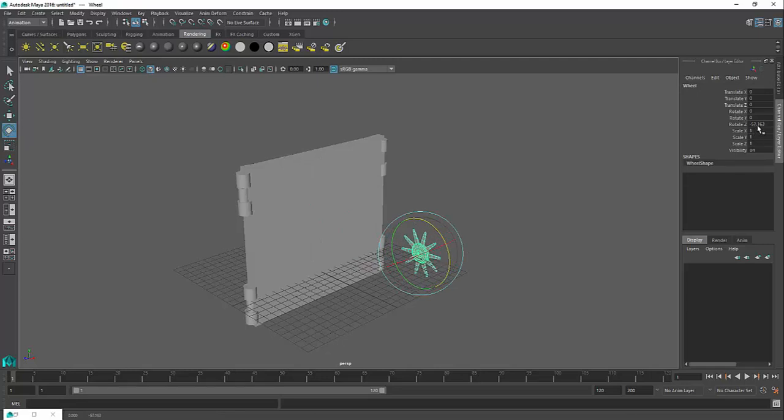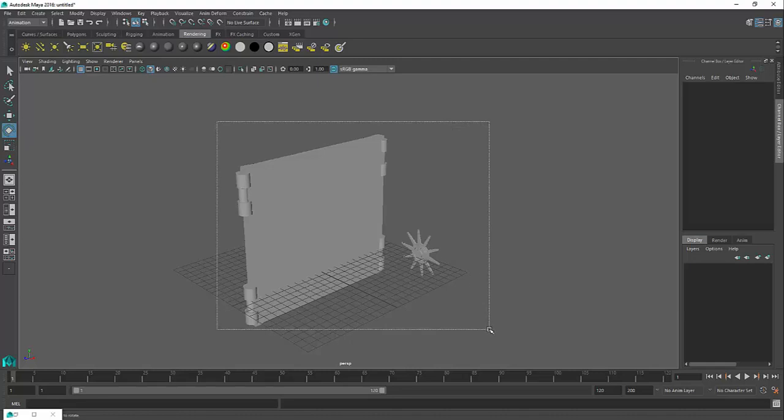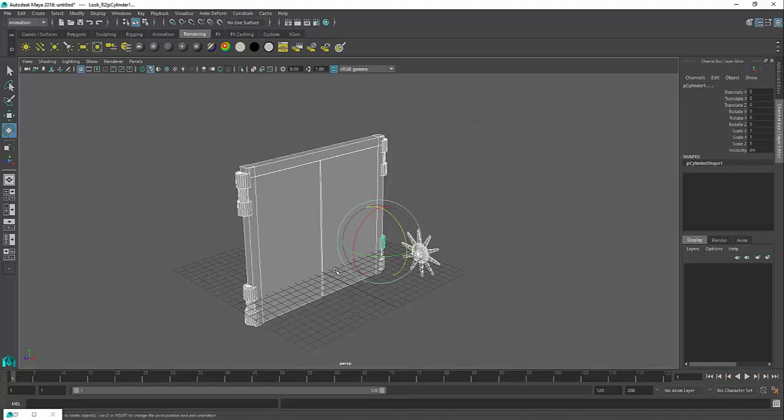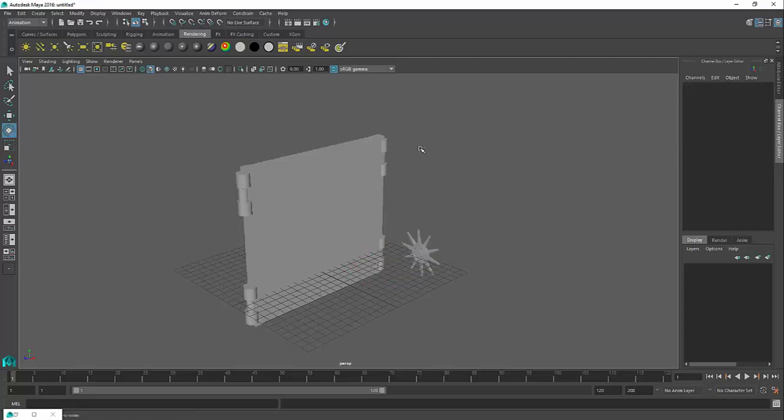As you can see, minus 57, I can clearly see. Just imagine if this object is already at minus 12. From minus 12, when I move it, it adds to or subtracts from that value. So it's going to be really tough to calculate what the initial point is. So it's always better to ensure that all the objects you have selected in the scene are zeroed out, so that you don't have a calculation issue.